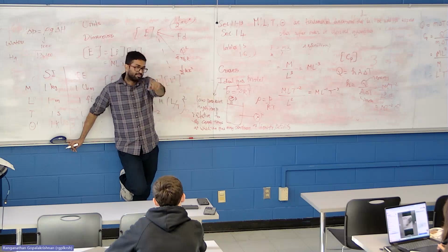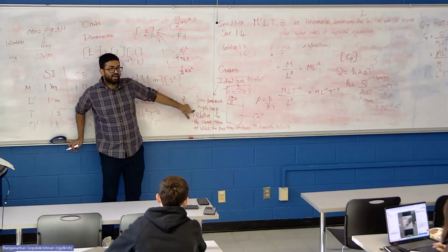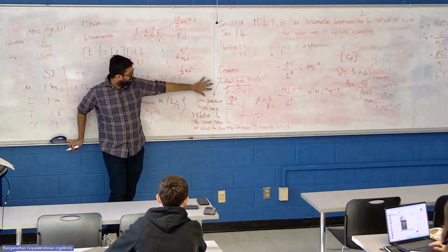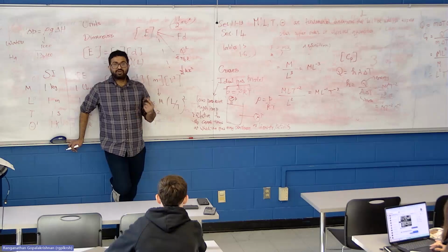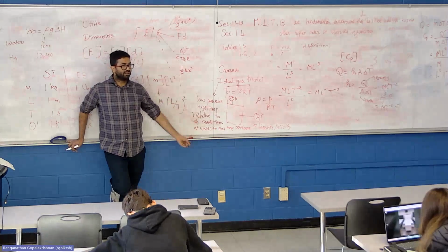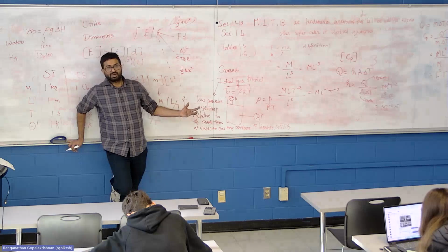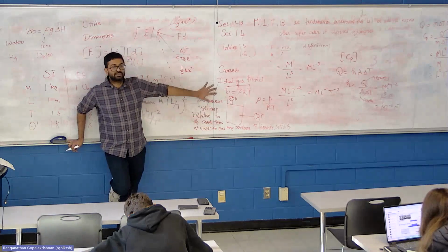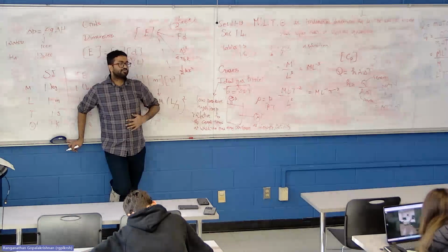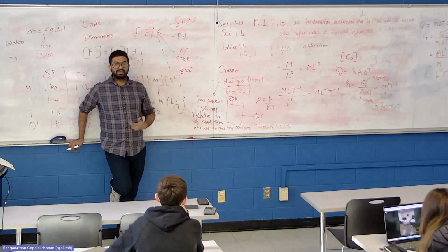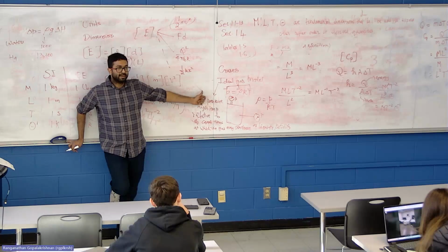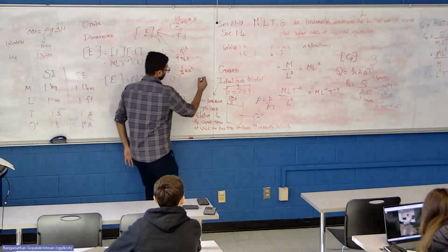It makes sense? The brilliant insight is it's a good model for low pressure and high temperature relative to where it will condense. Okay, so throughout our discussion in this course, if we encounter gases, we are going to deal with only atmospheric pressure or nearby atmospheric pressure and nearby room temperature. We are not going to deal with low temperatures or cryogenics or such exotic situations. So for us, this is a very good model for gases that we will use. That makes sense? For us, if you have to describe or calculate the density of methane at 2 atmospheres and 300 Kelvin, you can use the ideal gas model. It's a pretty reasonable way to do this. Okay, so this is covered in section 1.5.